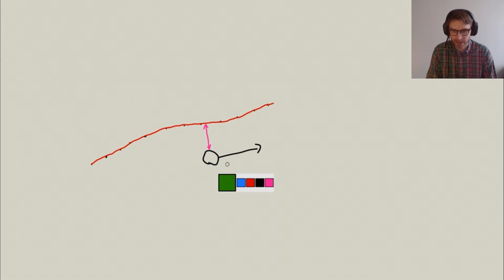Now, what is then the output of the controller? The plant is the turtlebot, then the error is the cross-track error, and then the output is the angle where we're trying to, let's not make it so steep, let's make it like so. And so it's the angle between the current heading and steering to the left. So the bigger this cross-track error, the bigger the steering.